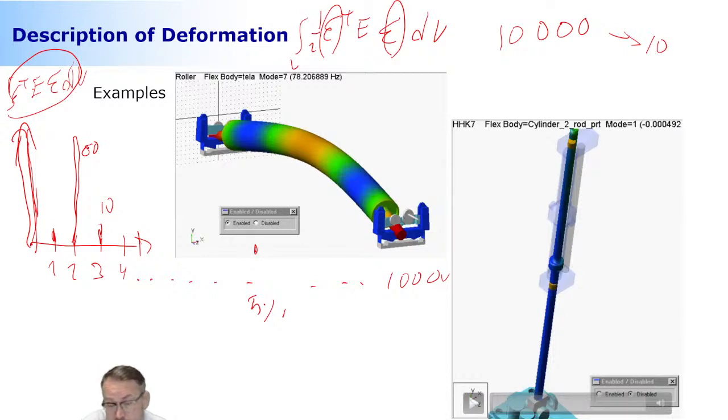Of course, this is a hypothetical graph, but it's common that one of them is mainly responsible for the strain energy, 80%, 50%, or more than that. The rest could be very insignificant. And the ones that are very, very small, super insignificant, you can get rid of them. And the damage you get in terms of accuracy is not much. Yes, you still get an accuracy damage, that is correct.